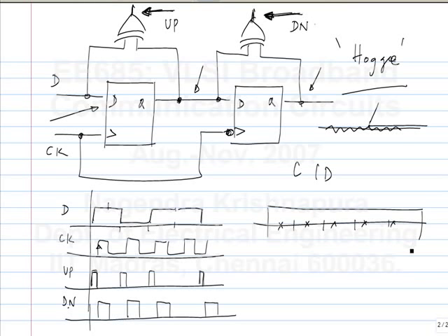So if you have a long enough string, the number of cycles counted by the clock can be different from the number of cycles that actually happened in the data. So the next time you sample it, you are getting the wrong number of digits out of the clock and data recovery circuit.